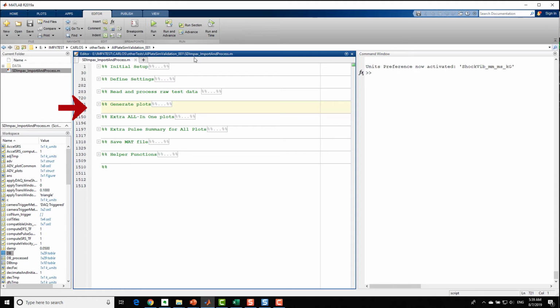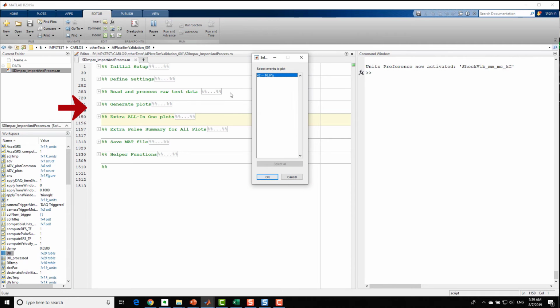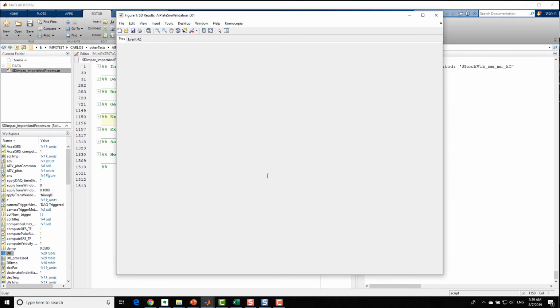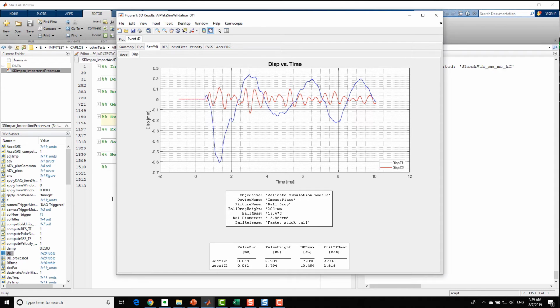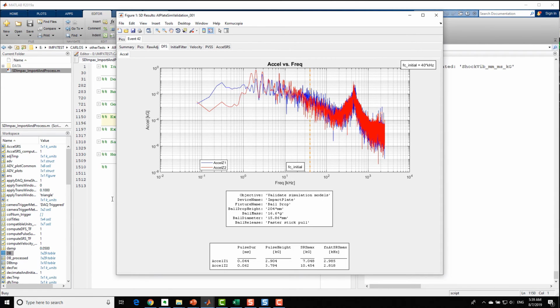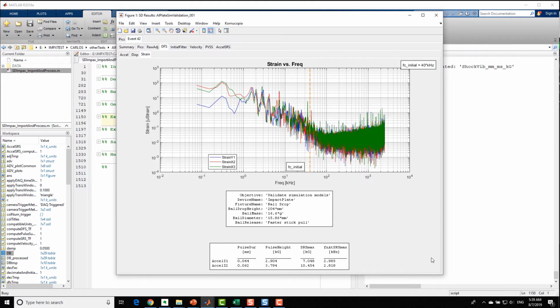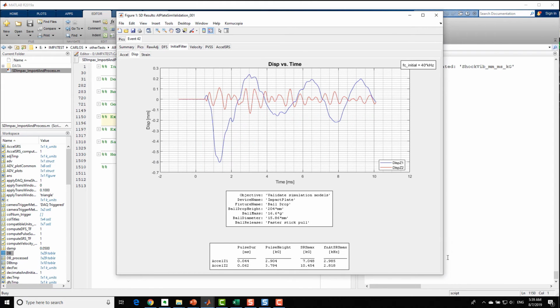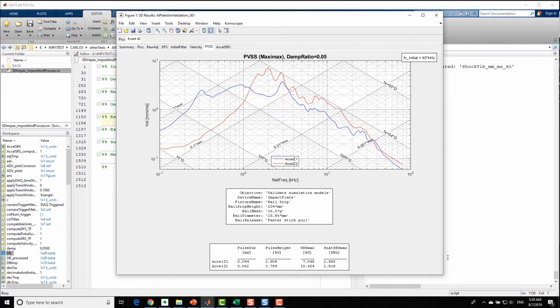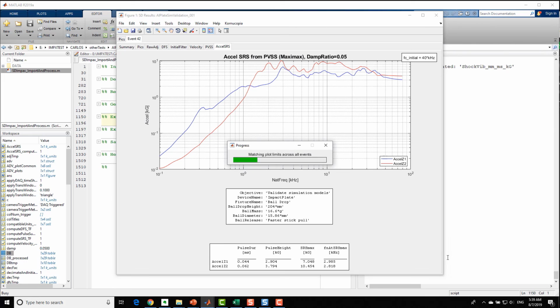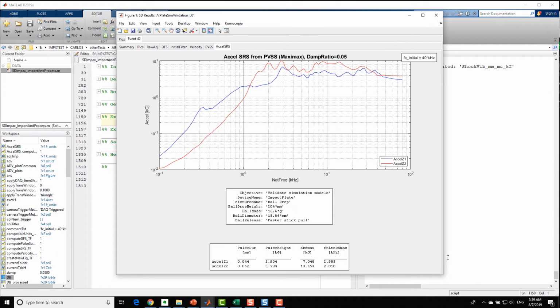Running the next section directs the script to automatically plot the various entities, including raw data after it is adjusted to remove DC drifting, discrete Fourier spectrums, low-pass filter results, velocity derived from integrating any acceleration containing columns, and shock spectrum curves computed from the acceleration data. Remember, all of these quantities come from the calculations performed in the script.